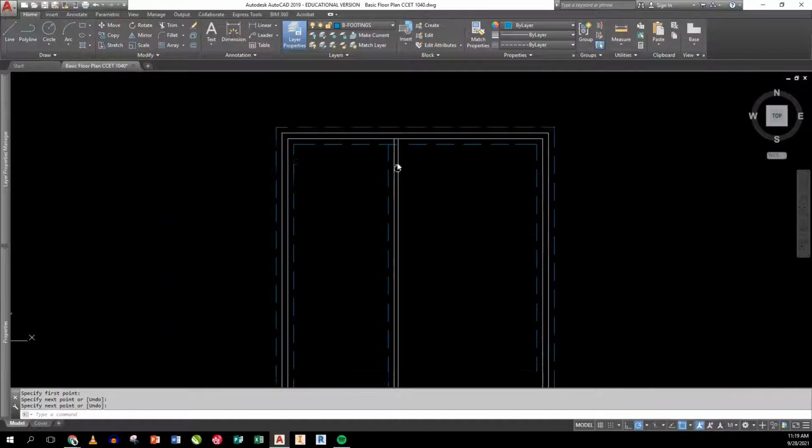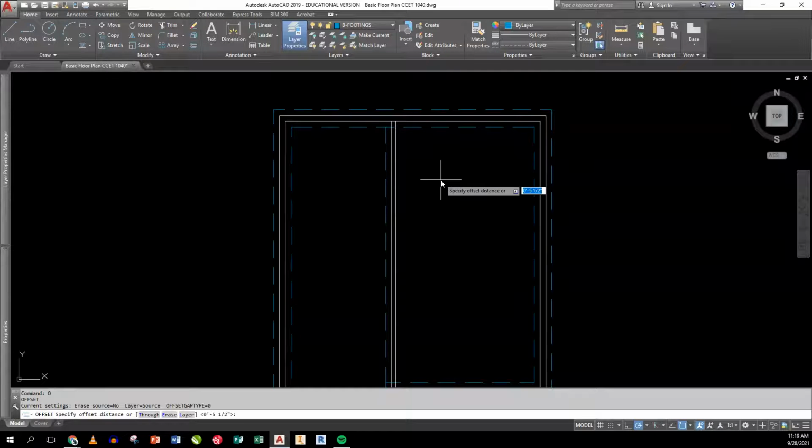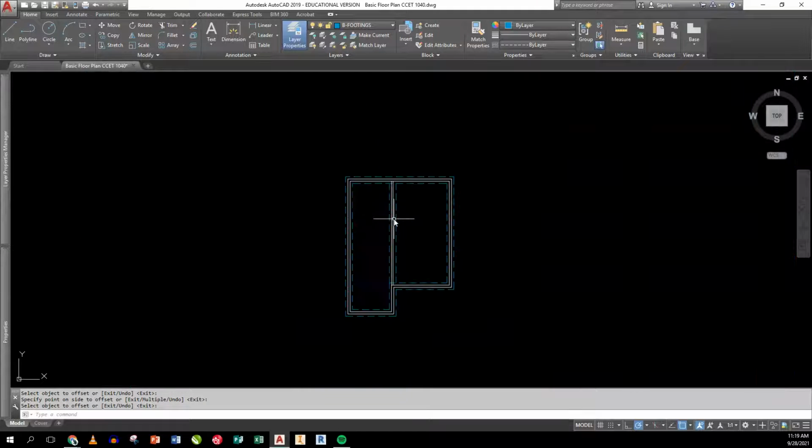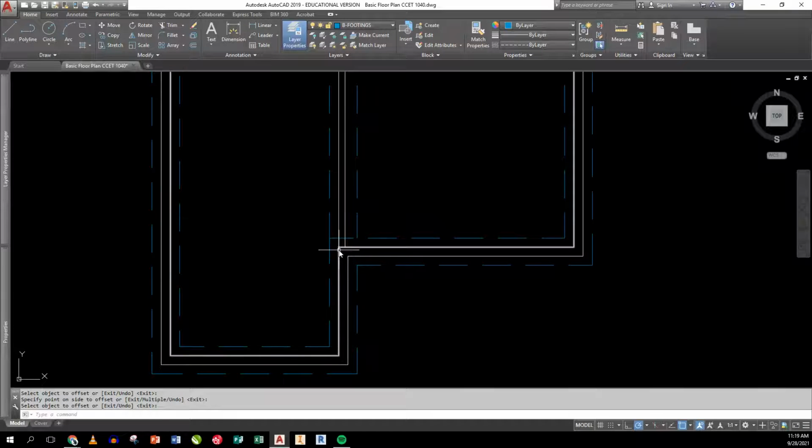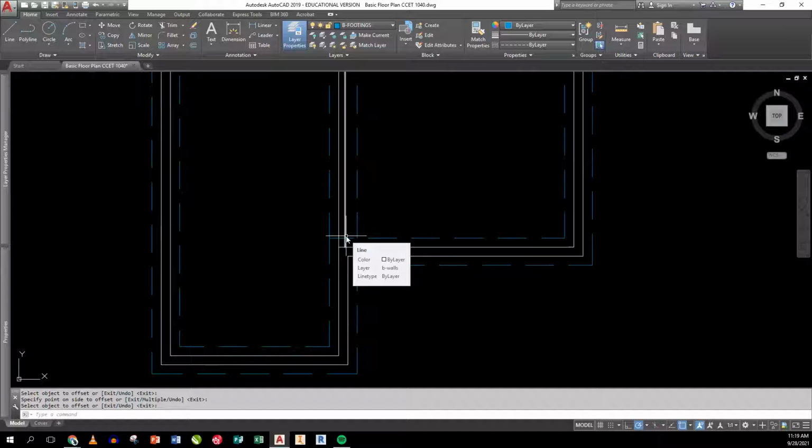Now, here's the bad part. This footing offset still has to be 24 inches wide, typically, to the bearing pressures we need. That makes it an asymmetrical footing. So here's my question. Do I move this over, or is it okay with an asymmetrical footing?